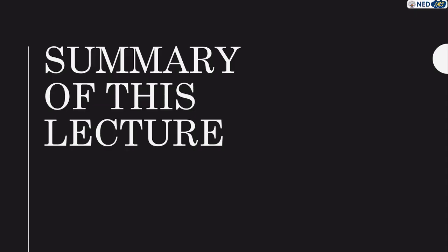In the end, the summary of this lecture is that we did the 2's complement representation, or the binary representation for signed numbers. The benefit of 2's complement is that we can represent negative numbers as well as positive numbers in binary, and if we want to subtract two numbers we actually do addition. Also, we did the ranges of signed and unsigned numbers in this lecture.